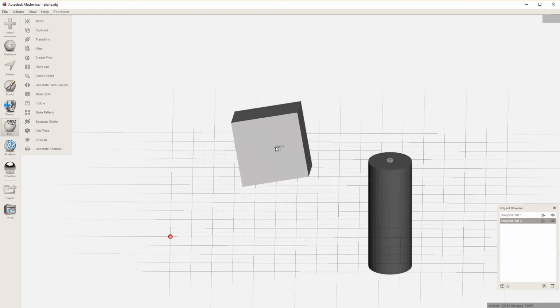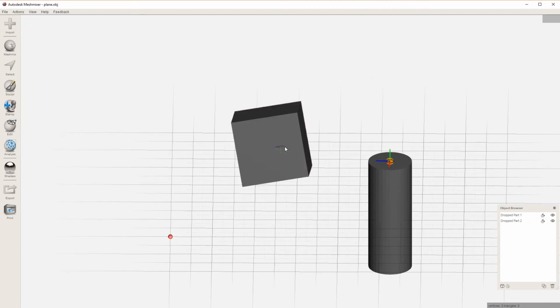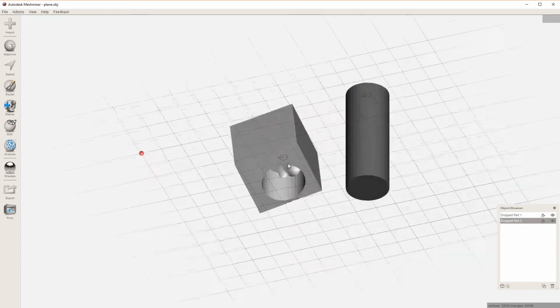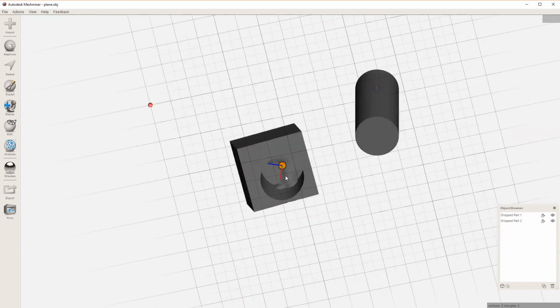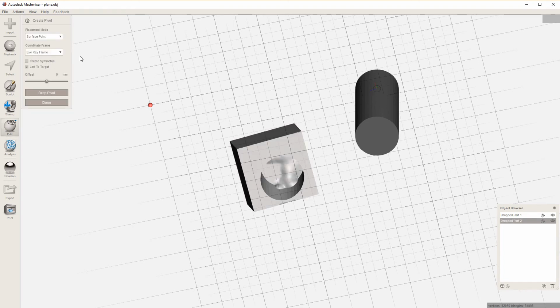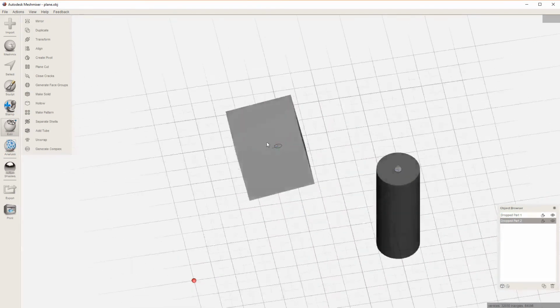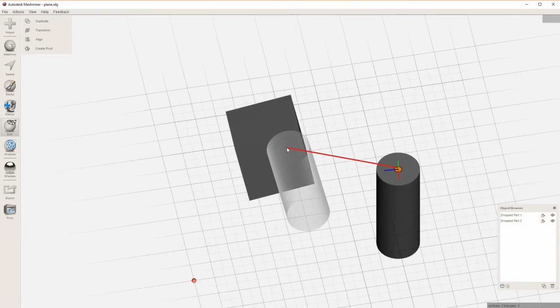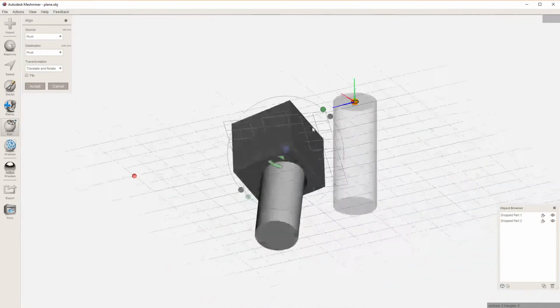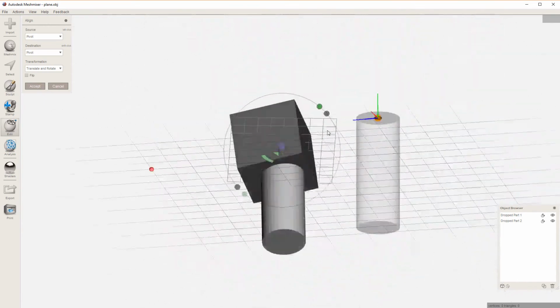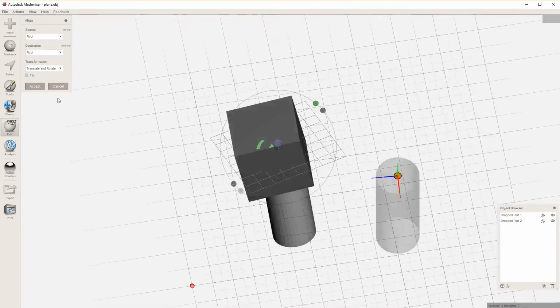You should be able to see that this was an issue. This is actually a good thing to bring up. When I created this pivot right here, I didn't have link to target on, and so it wasn't actually linked. So I'm going to drop it there, and now it is linked. Okay, you should be able to go like that. And now I have moved that there. See, it's not perfectly aligned, but if the pivots were aligned, it'd be nice.